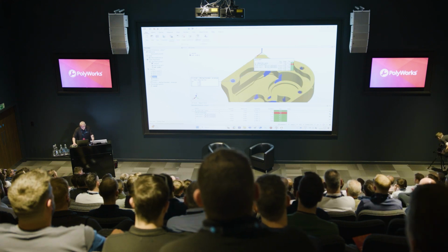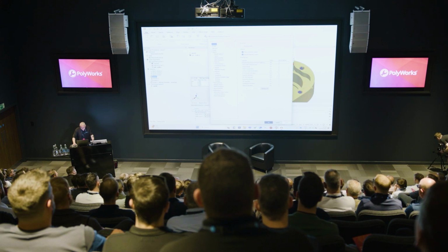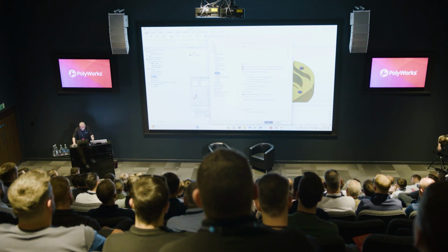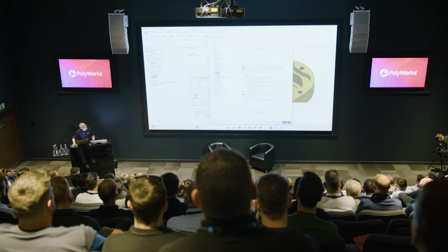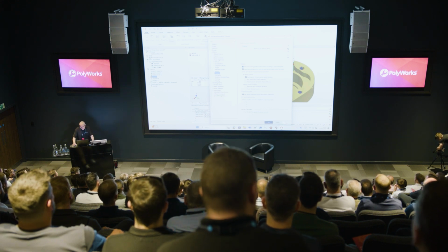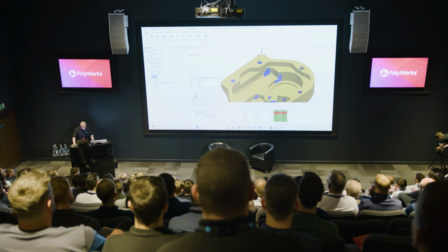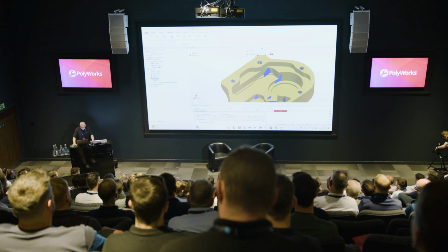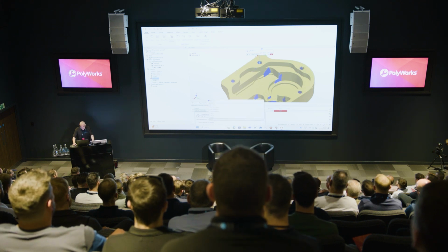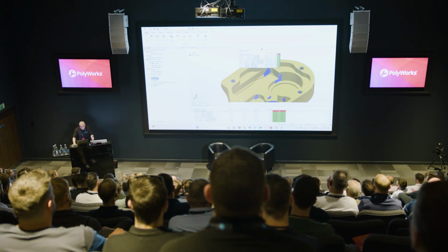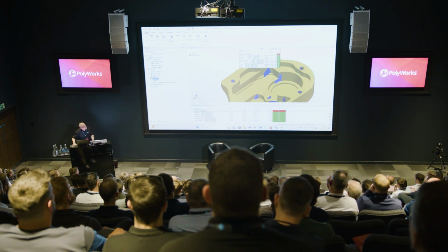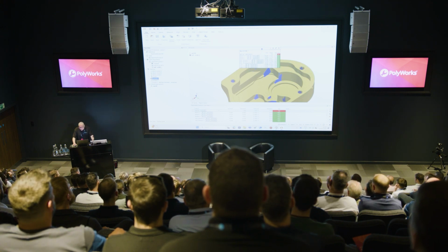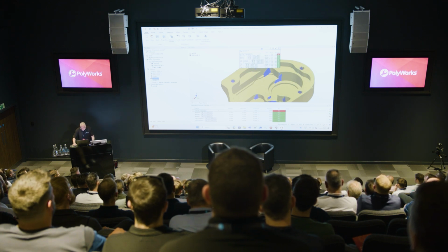So under the options, objects, controls, in there we can actually add that in as a standard value in our annotations. Similar for the cylinder. If we go into the cylinder, we can add in the X, Y and Z positions top and bottom, and we can also add the max deviation. What we'll find there is that the max deviation in the case of ASME matches either the top or the bottom values. In this case, it's the bottom values.